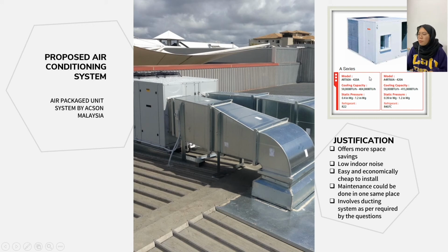The air package unit that I have chosen is from Accent Malaysia, the A series with a model of RART100E, having a cooling capacity of about 100,000 BTU per hour.